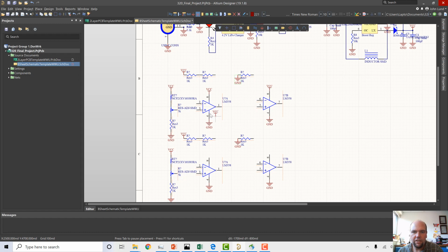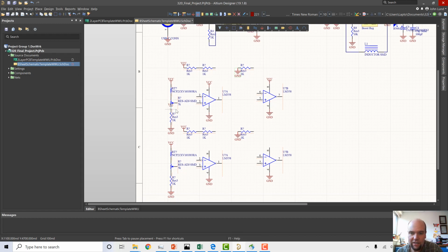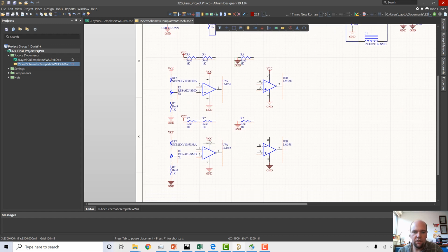So one thing to note is we show 2 physical op amps. These 2 physical op amps are both the same, basically they're 2 parts on the same package. So you'll see pins 4 and 8 are labeled the same. So I don't think we actually need to put labels on both of these. They just have to be consistent. And I'm not even sure that's the case. I've never really tried it. So I think we're, oh yeah, we gotta put rails over here too.